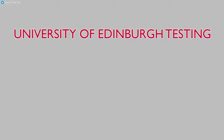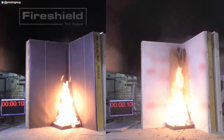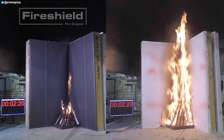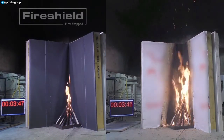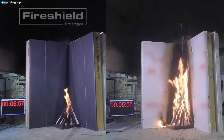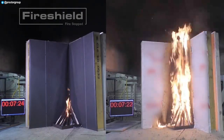In this comparative test conducted by the University of Edinburgh, based on the EN 13823 single burning item test, the Fire Shield on the left reacts substantially less than the other Class B fire-resisting membrane on the right. The surface of the Fire Shield acts similarly to an intumescent coating, frothing up to protect the insulation boards and structure. In this test, the unique coating protects the sheathing long enough for the external fuel source to be exhausted and for the fire to self-extinguish.